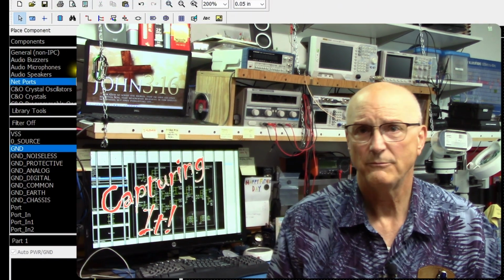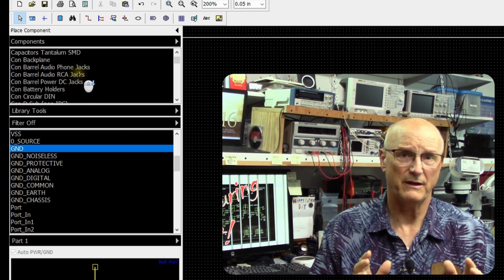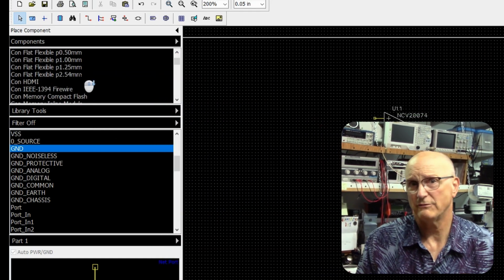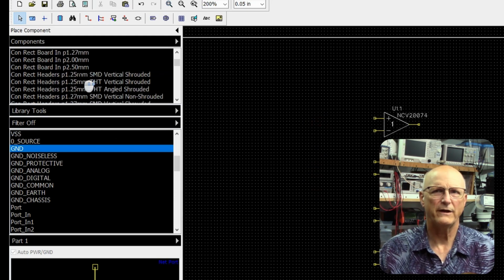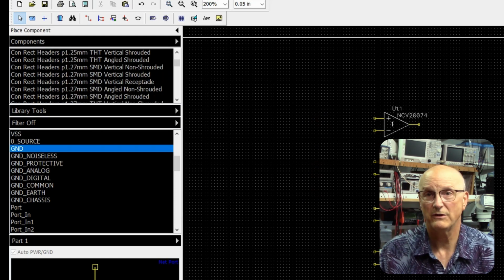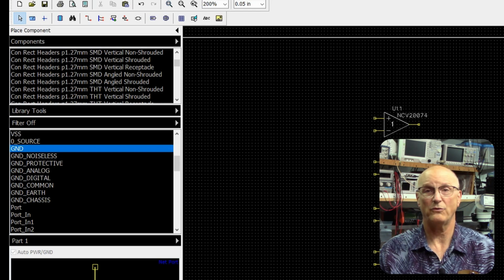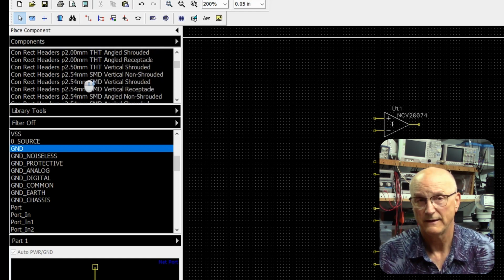Because this board is going to reside on the front panel and the input connectors are going to live on the back panel, the connectors will not be mounted on the PCB itself. My input connectors are just going to be a place to solder shielded cable to. So an appropriate 2-pin 0.1 inch or 2.54 millimeter pitch connector footprint will work just fine.